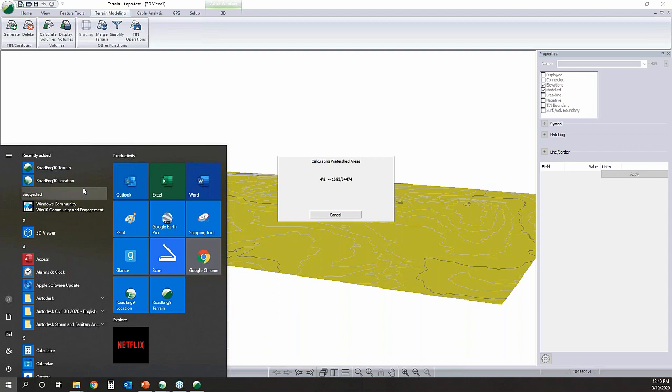If you use your stationing from the P-line, you can have the road, your topo surface, as one file, and your P-line as a separate file, and you can reference both of those in location and version 9. You could also use other data types with the LiDAR and augment your LiDAR data sets with additional points. You can drop the P-line data set into your LiDAR data set as well, but that can be somewhat tricky depending on how accurate things are. If one data set is really accurate and it's a poorly done P-line survey, they might not match up perfectly.